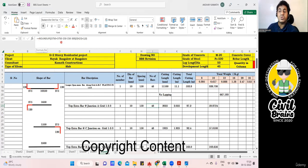3750 plus 3750 is 7500, minus 150, minus 150, minus 300 for the center beam, divided by the spacing. The spacing is 150. Whatever answer we got, we should take plus 2 because we are taking two spans simultaneously. So I've taken plus 2, close the bracket, give a comma 0, close the bracket, hit the enter button, finish. 48 number of bars is required. Finish. Cutting length you found. Number of bars is found.